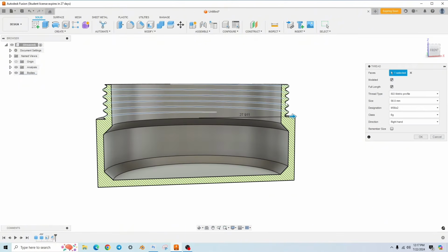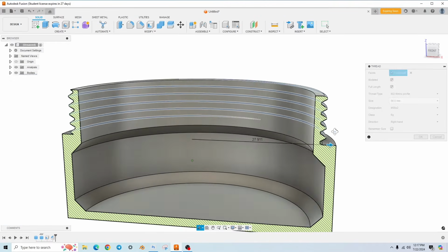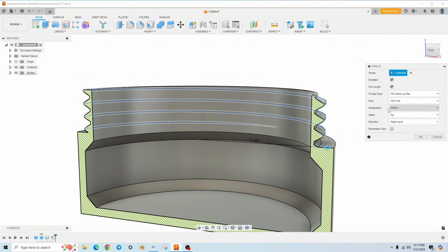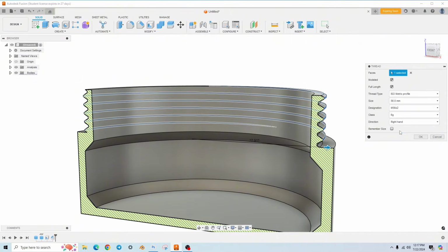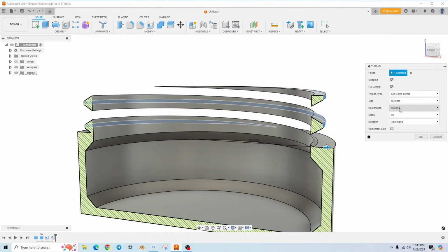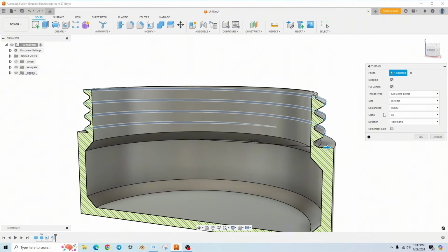And now you can see that's definitely a lot thicker. Usually when I use the thread tool, I never go past M2. I actually really like to be in the M3. M2 will work just fine. You just may have to increase your allowances a little bit. I have found that the bigger the thread, so M5.5, M4, the larger the thread, the less tolerance you need.